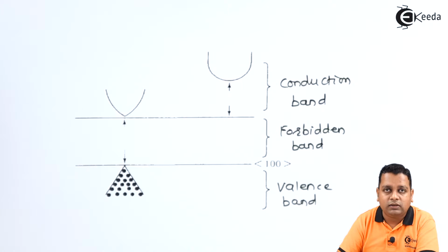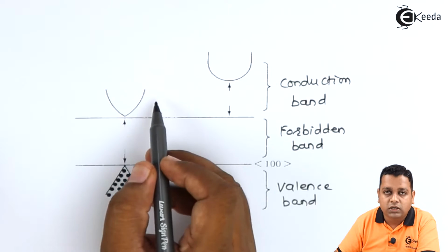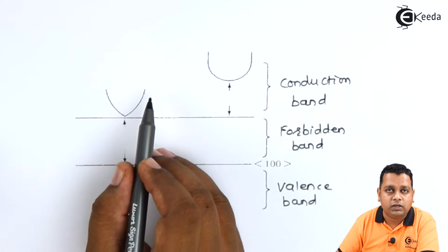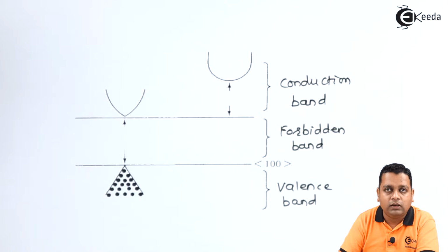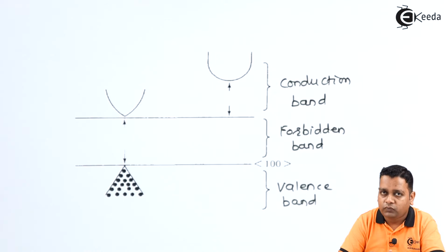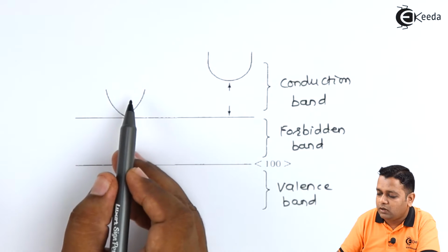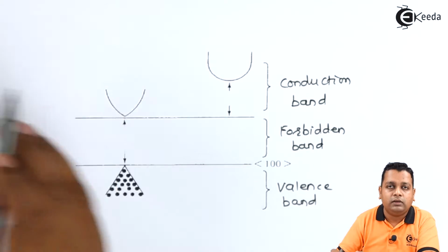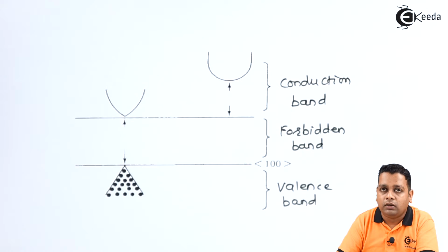Once the charge carrier is shifted from the valence band to the conduction band, it will be free to move inside the bulk, constituting the current here. So initially it is very essential that whatever electrons are associated with the atoms and molecules, with respect to whatever bonding structure is present there, they have to shift from the valence band to the conduction band, and inside the conduction band we shall be discussing the exact operation of our typical Gunn diode on the gallium arsenide n-type semiconductor material here.